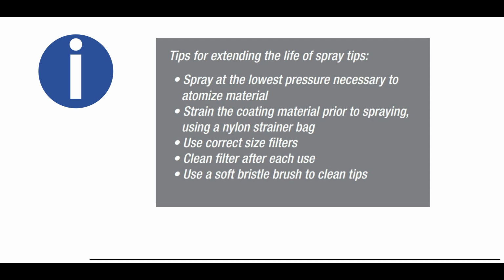Tips for extending the life of spray tips. Spray at the lowest pressure necessary to atomize the material. Strain the coating material prior to spraying using a nylon strainer bag. Use correct size filters. Clean the filter after each use. Use a soft bristle brush to clean the tip.